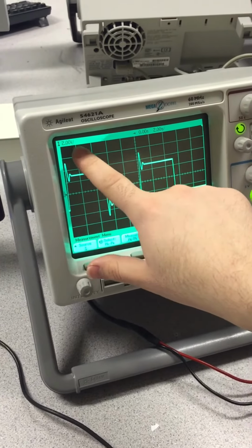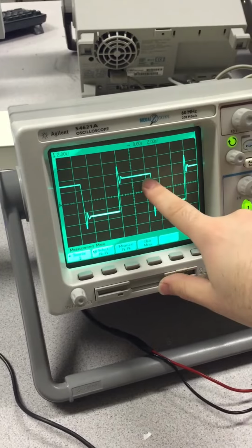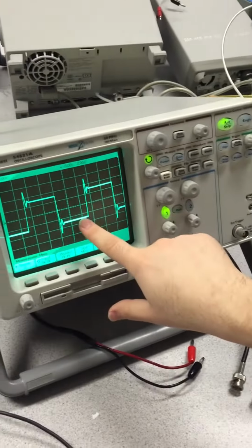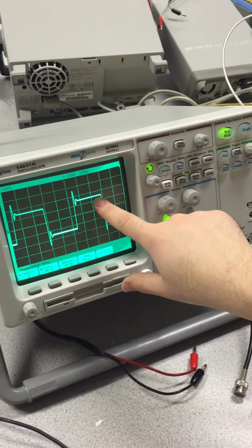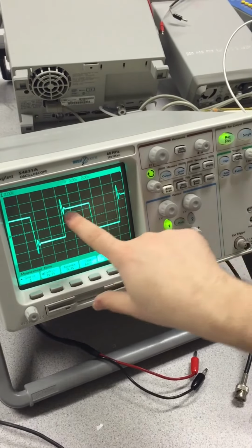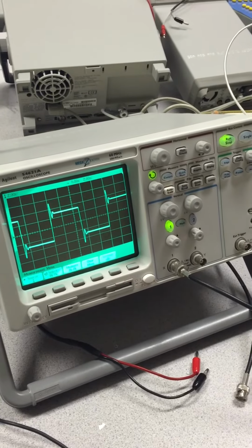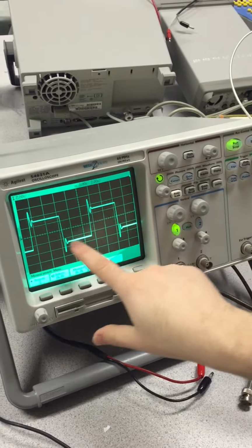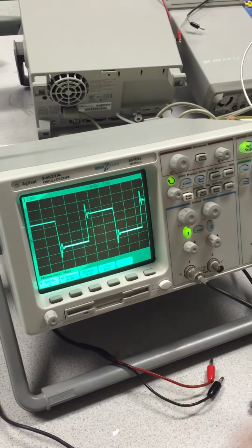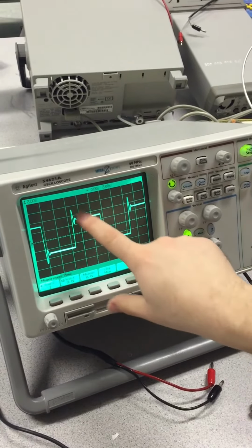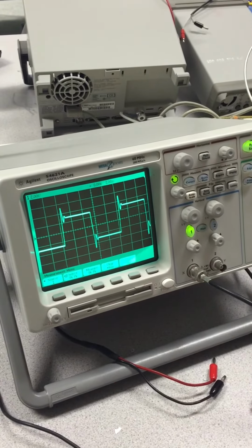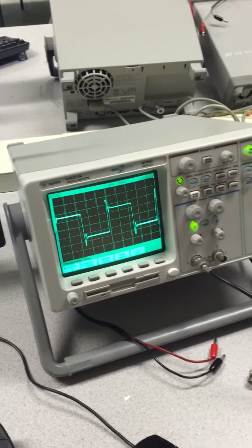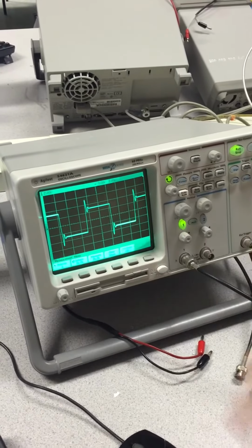This is 2 volt per division, so this one is the 3 volt. Remember that the input here is 6 volt peak to peak, so we have 3 up and 3 down. So the angle actually rests in the positions that we want. We input 6 volt peak to peak, and the angle ends up 6 volt peak to peak. The amount of overshoot here depends on the constant of proportionality. We just make k equal 1 here, and we have around 40% overshoot.